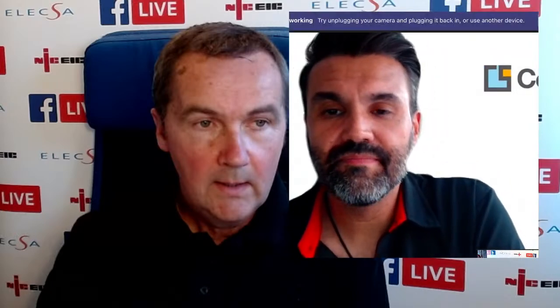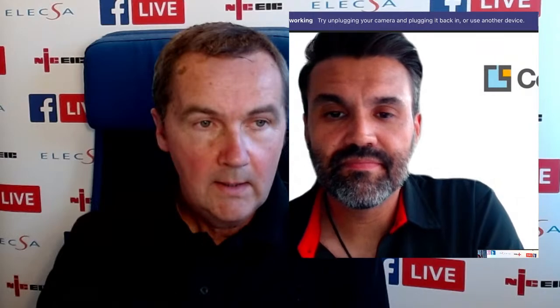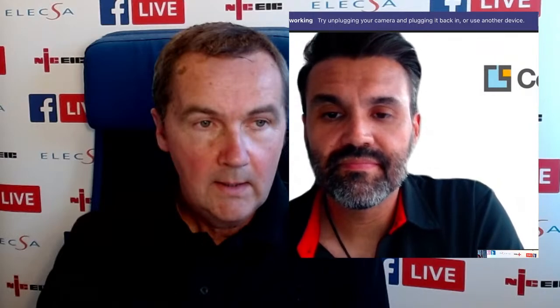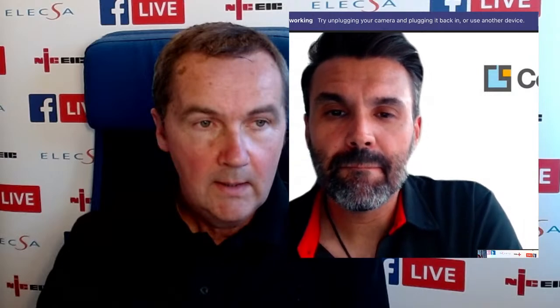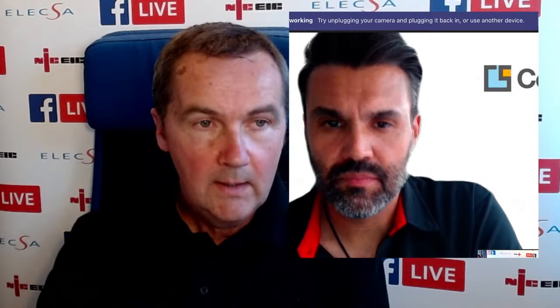Question from another engineer: Evening guys, is an unswitched fuse spur acceptable in a wet room for an extractor fan? Okay, we would need a little bit more information, because whereabouts in that wet room, inside the zones or outside? But potentially yes. The fact that it's unswitched would mean you could get it a bit closer, but we'd need to know exactly where you were thinking of, because it would need to meet the IP rating if you were to put it in the zones, and even outside of the zones.